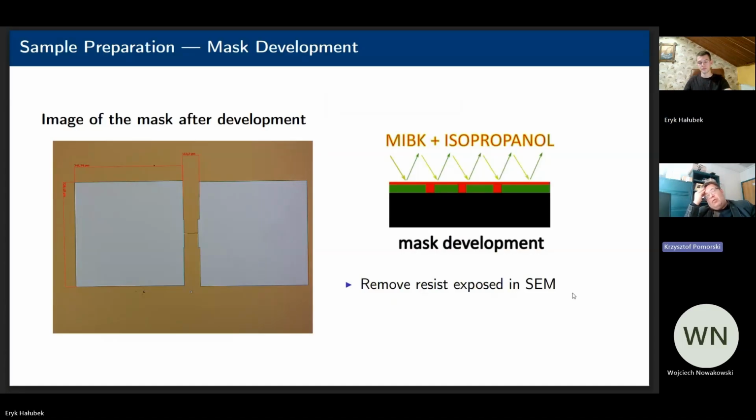So in a sense, the red one is the place of the resist exposed to this beam of electrons, where the polymer chain is affected and partly destroyed. Yes. But this is important also that the place where you see the green area was not exposed to a beam of electrons, but it is also slightly affected by this chemical, but not as much as the place where there was exposure to electrons.